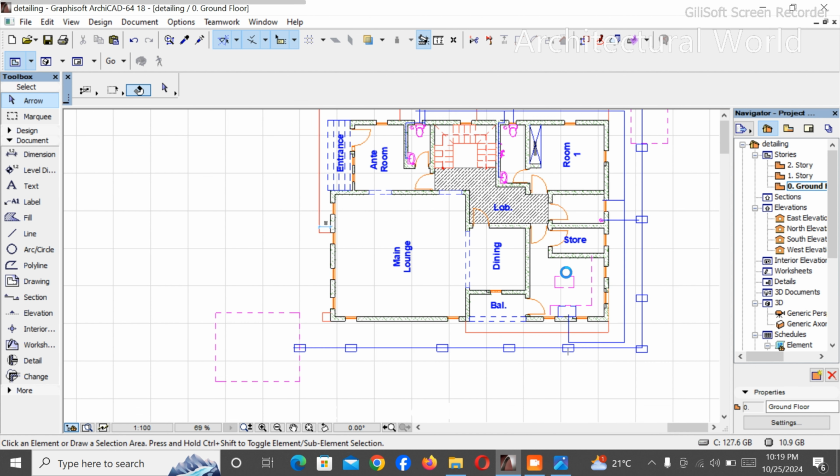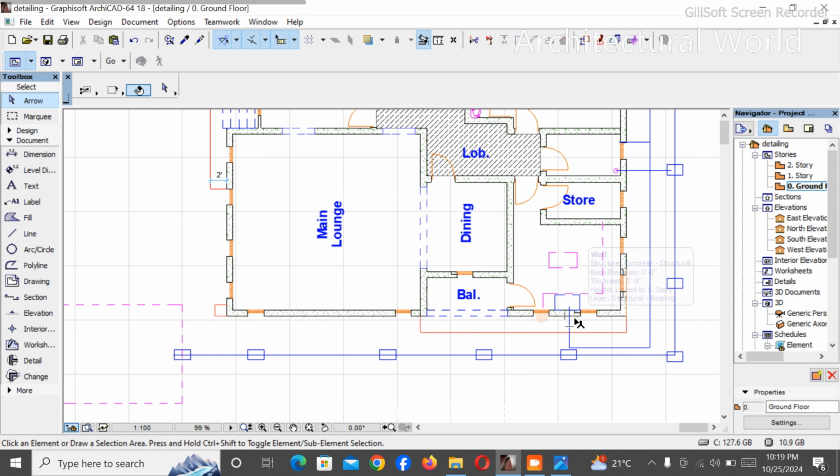And besides, since this is just waste, that's why I said most of these mechanical jobs you do on ground. That's why you have to be grounded in all these jobs. If you check this kitchen very well, this is basically just waste. And if you don't want to experience any future blockage, you have to use 3-inch pipe to discharge this sink.